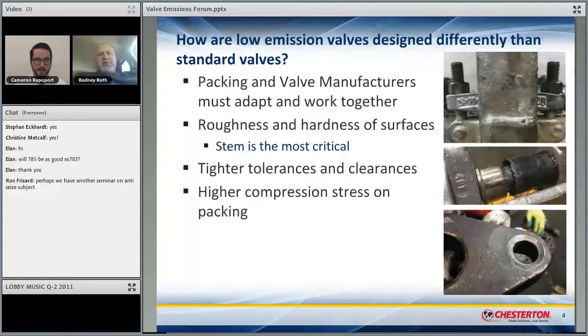The second picture you see there showing extrusion, that's relative to the design criteria that has been established by the API to give people guidelines for manufacturing valves. And I'll use one size in particular. A 4-inch 300-pound gate valve has a 1-inch stem and a 1.5-inch bore.